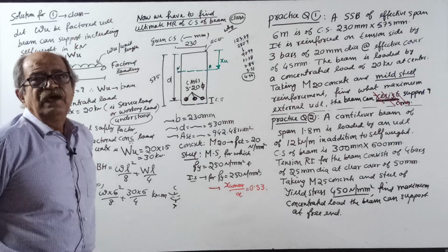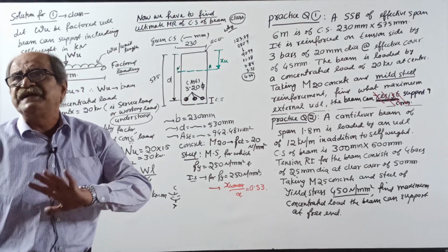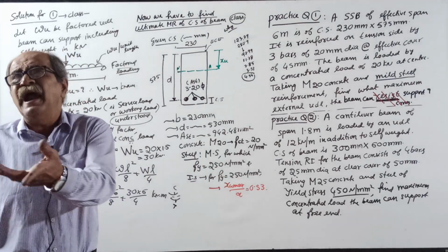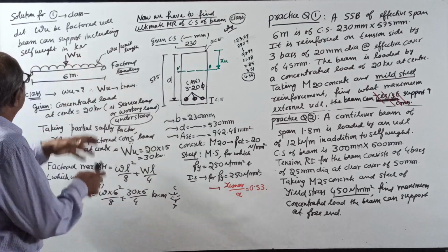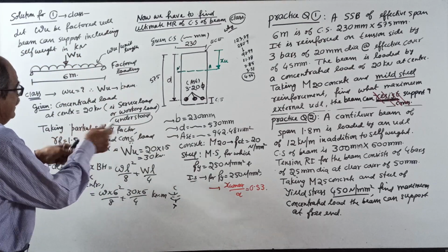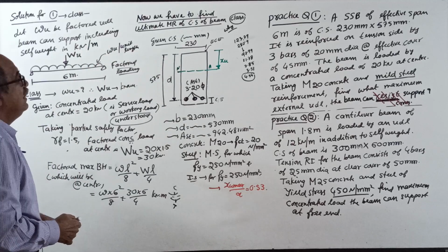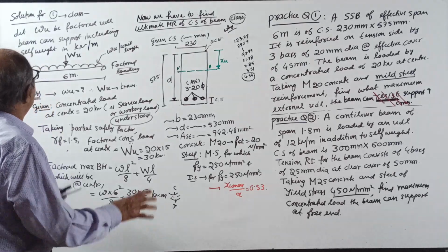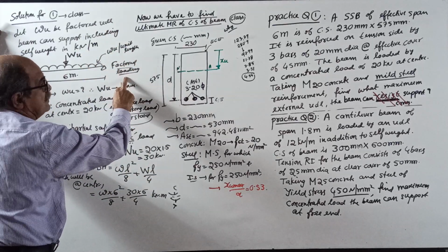What you will do is, suppose the answer for the beam's external UDL is 10. You won't get 10 now; you will get 13. Then what you do? Subtract that 3. That's all. Including self weight in kilonewton. Oh, sorry, it is not a point load; the unit will be kilonewton per meter UDL. Okay. Now, write what is the final factored load for the beam.